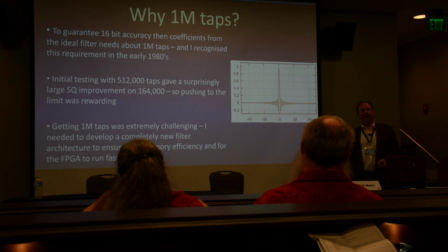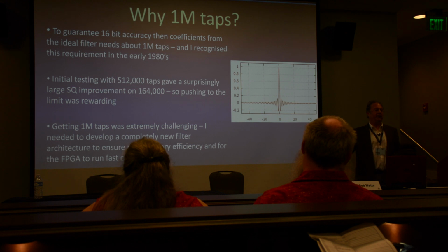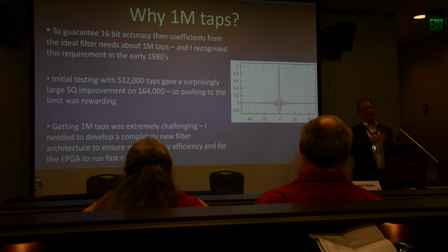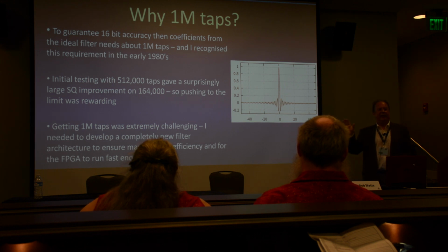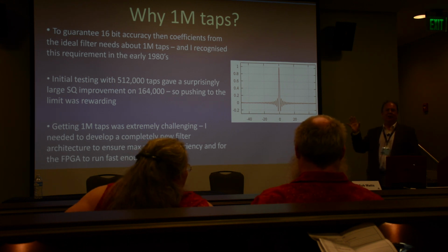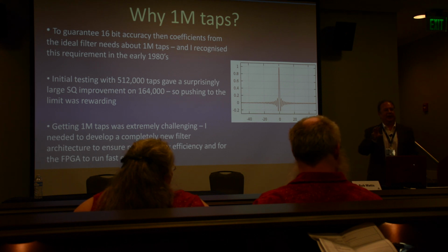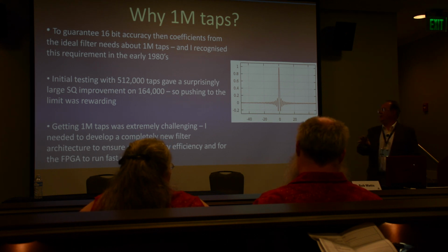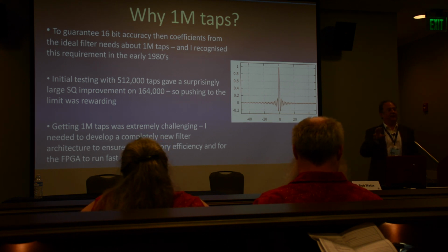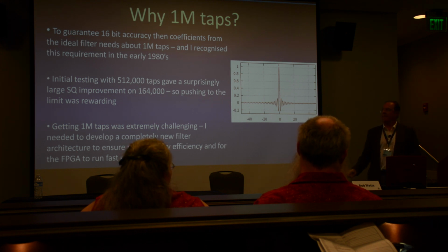A few months later, we were doing Whittaker-Shannon sampling theory, and they were saying digital audio is fine because you've got this sampling theory that proves it, and you need a sinc function and you recover everything perfectly. But we didn't have FIR filters, we just had ordinary LC filters. And I realized that immediately you would not be able to recover the transient timing information properly. And this would be a fundamental flaw of the whole system.